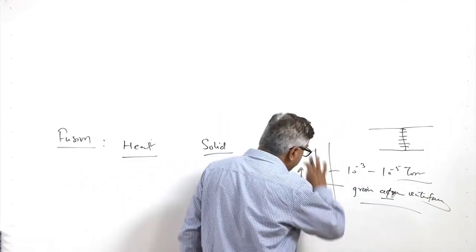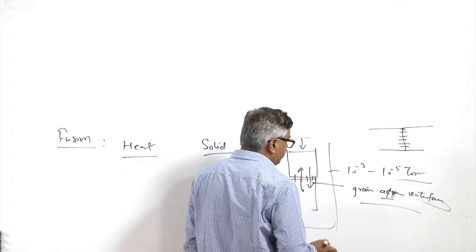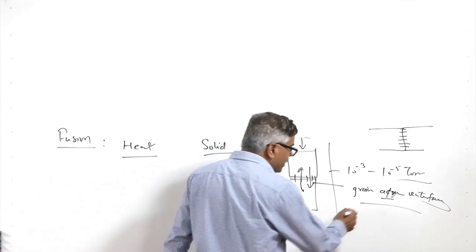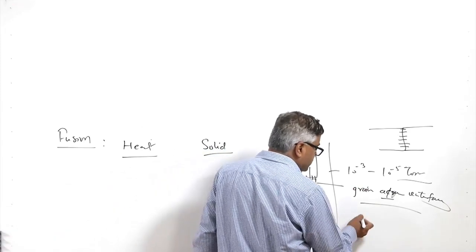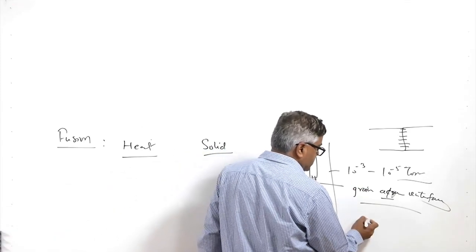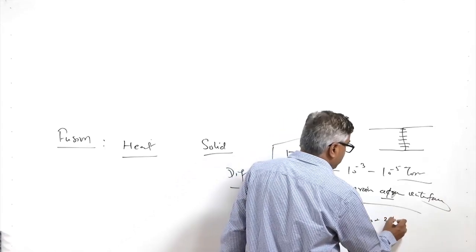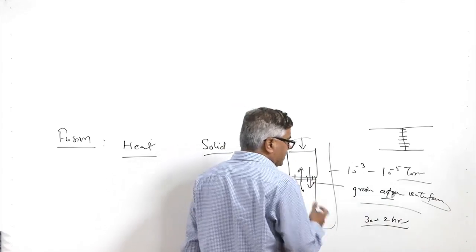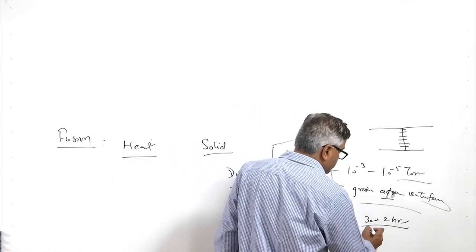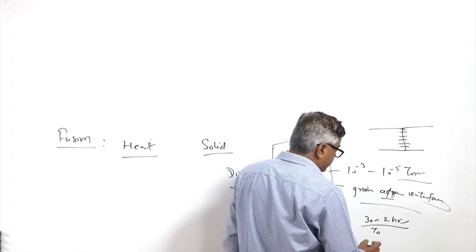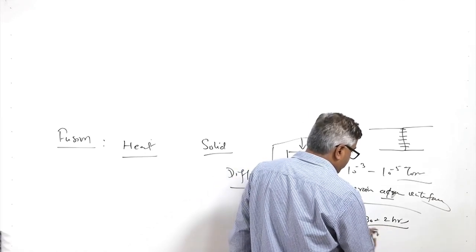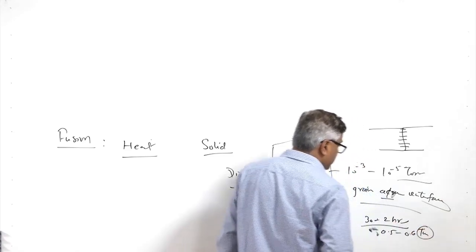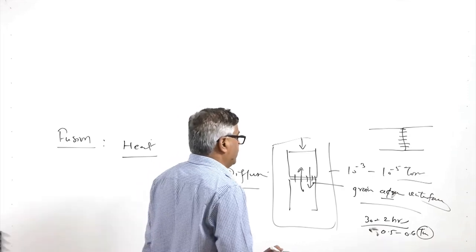so that in turn leads to the metallurgical continuity. So heating is important to facilitate the diffusion, since the diffusion is a slow process, so it takes time. So we need to provide enough time so that diffusion can occur across the interface. Normally 30 minutes to 2 hours time it takes to have the kind of metallurgical continuity across the interface, and the temperature can vary in the range of say 0.5 to 0.6 times the melting point of the metal in Kelvin.